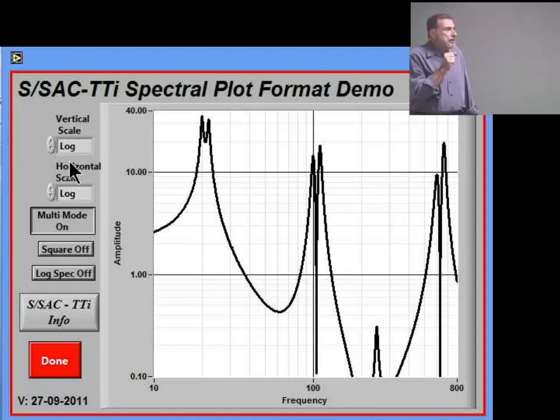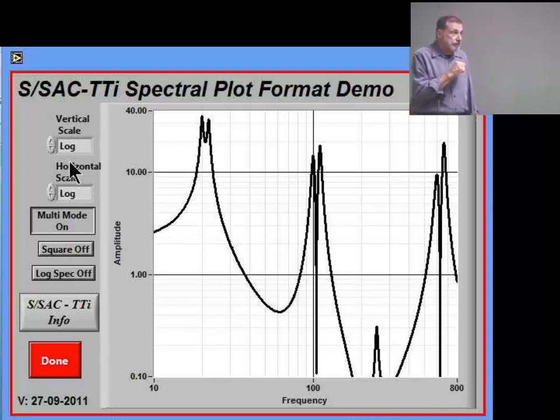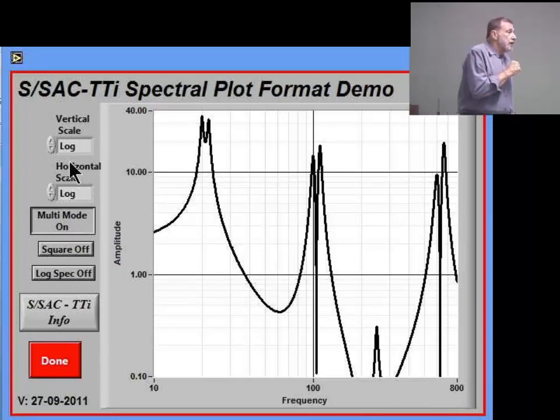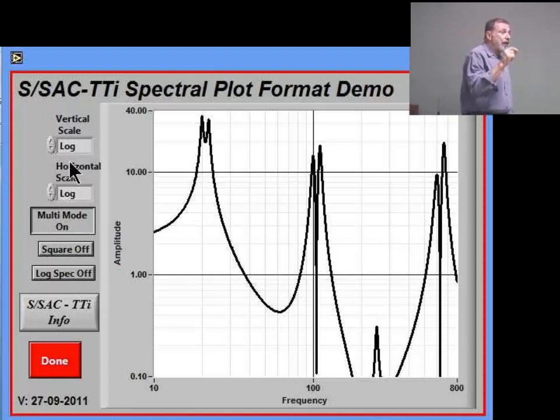Which one do you want to use? Okay, what are you looking for? Let's say we were doing strain gauge testing. What's wrong with strain? Well, I shouldn't say what's wrong. What is a bad feature of strain gauge testing? I don't use strain gauges. Well, the signal is small. Yeah, okay. So the signal to noise ratio is going to be small. And also, it's strain or stress that causes things to break.